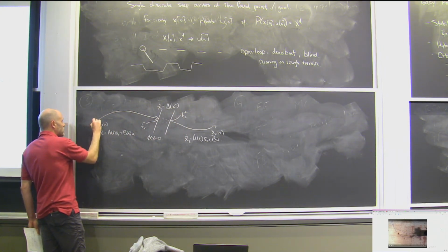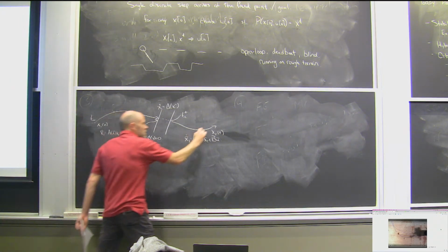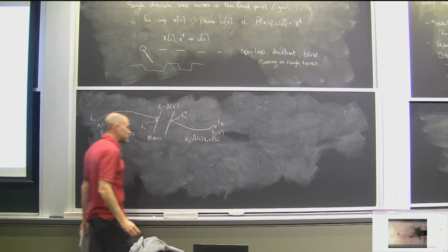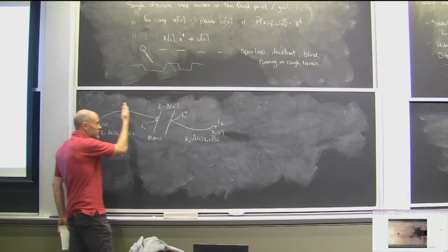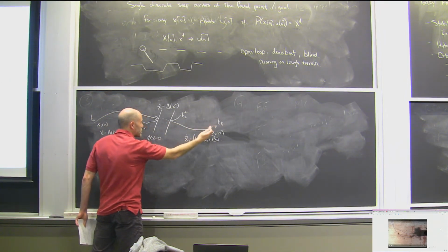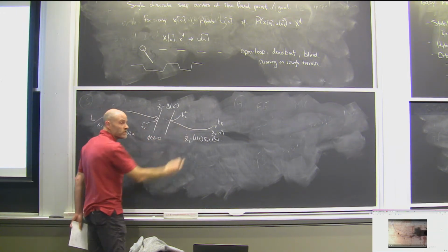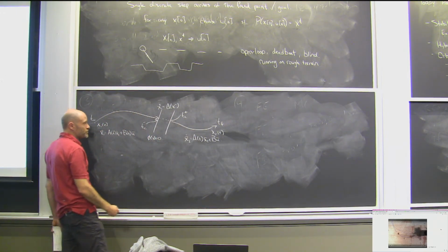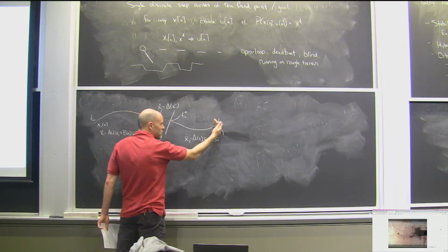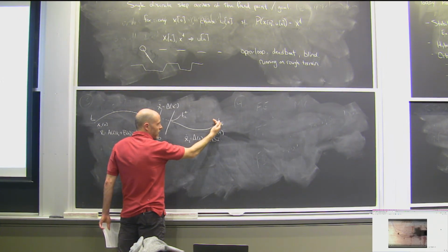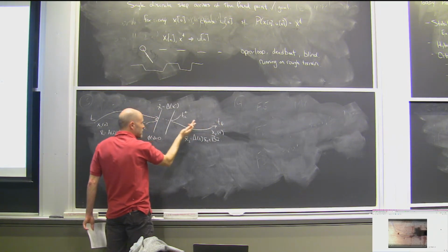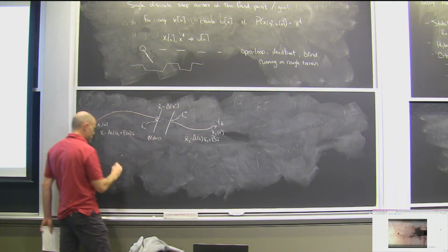I can call this, let's say, time 0, and this time final. What I'd like to do is come up with a finite horizon LQR strategy that works for this now hybrid system. And you can imagine that since this is a continuous trajectory here, the way I'll start is the same way I started with the finite horizon LQR. I'll start with a final condition on my Riccati equation, and I'll integrate back my Riccati equation at least to here, okay?